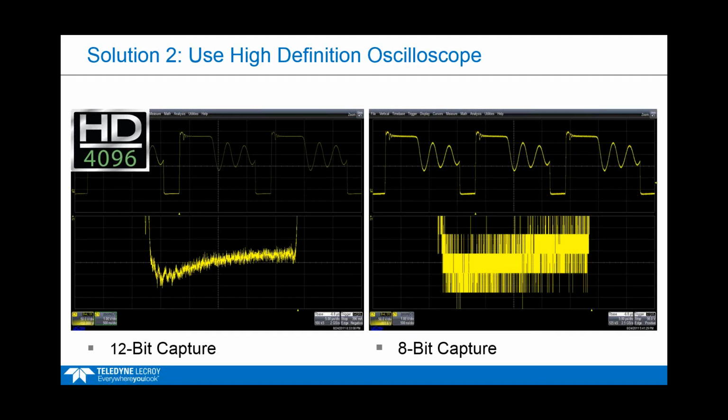So there's a second solution, which is a newer solution from LeCroy to solve this measurement problem. The DA1855 is still a great solution for this, but we've come out with a series of scopes now, which we call our high definition oscilloscopes. What the high definition scope has is a really low noise, pristine signal path front end, and then it has real 12-bit digitizers, 12-bit ADCs inside of the scope. So this gives us a much lower noise measurement with a much higher dynamic range.